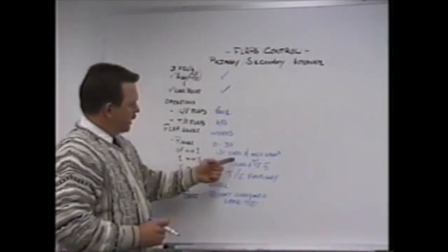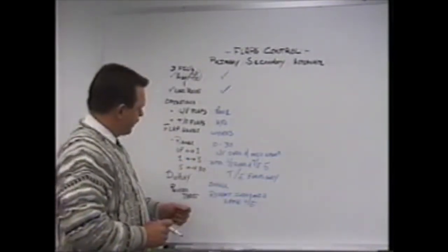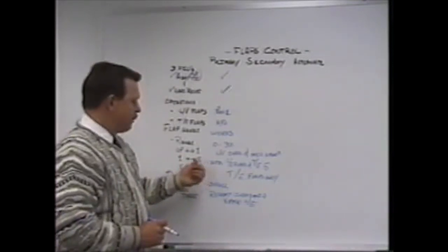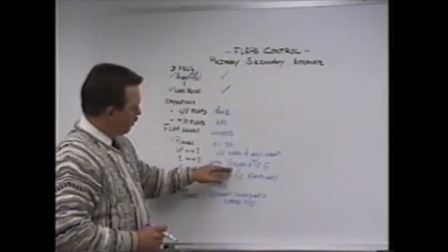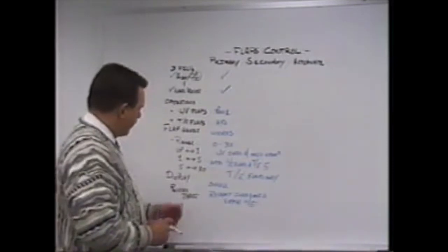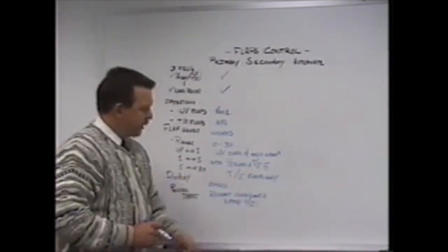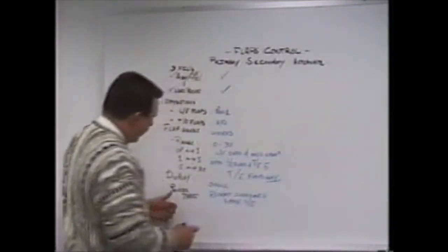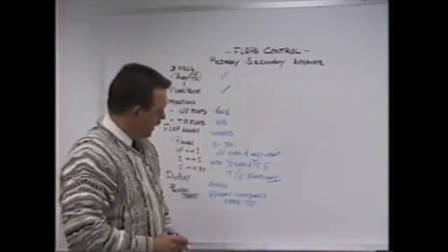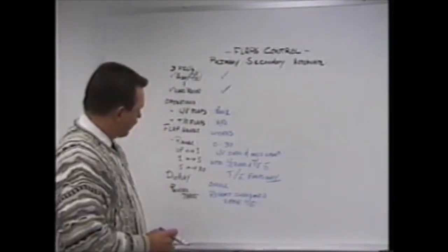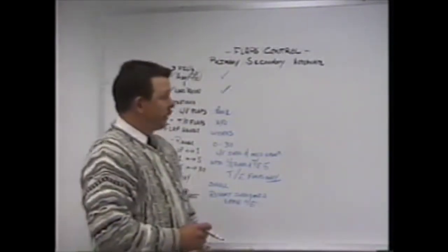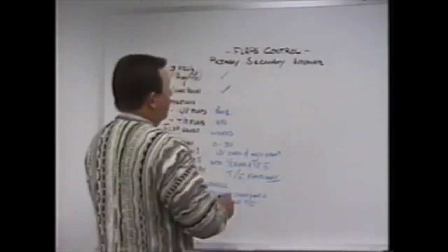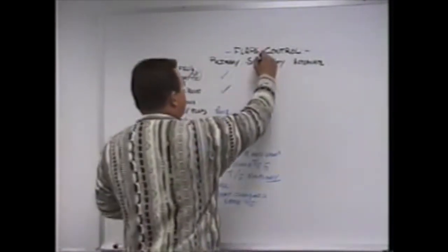Flaps up to 1, inboard and midspan leaders only. Flaps 5 to 1 or back either way: outboard leading edge flaps and flaps to 5. Flaps 5 or greater is just trailing edge flaps only. Going into reverse thrust, leading edge, inboard, and midspan will retract. Single vertical tape display. Secondary mode of flap operations happens automatically.